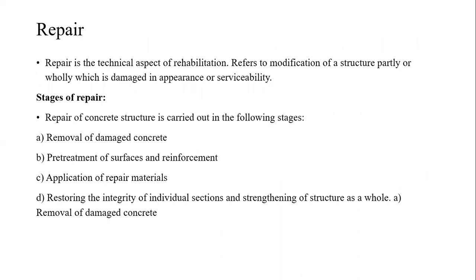It includes stages. The definition given here is: repair refers to the modification of a structure, partly or wholly, which is damaged in appearance or serviceability. The stages of repair include removal of damaged concrete and pre-treatment of surfaces and reinforcement, application of repair materials, restoring the integrity of individual sections, and strengthening of the structure as a whole. So these are the stages of repair.